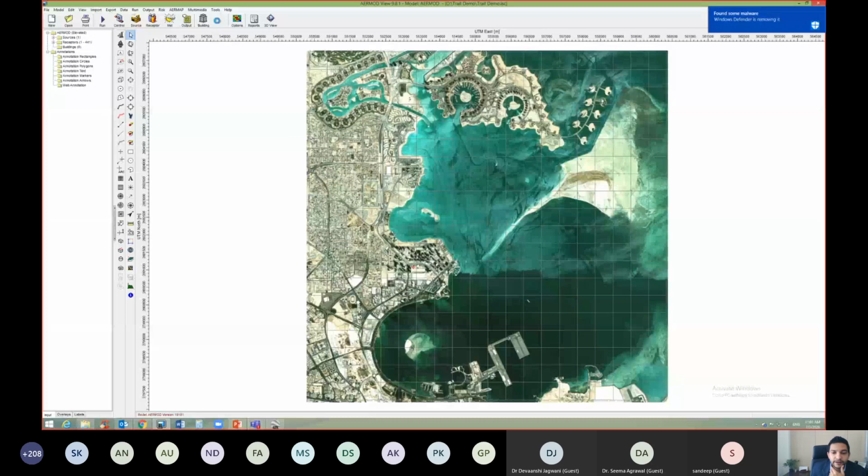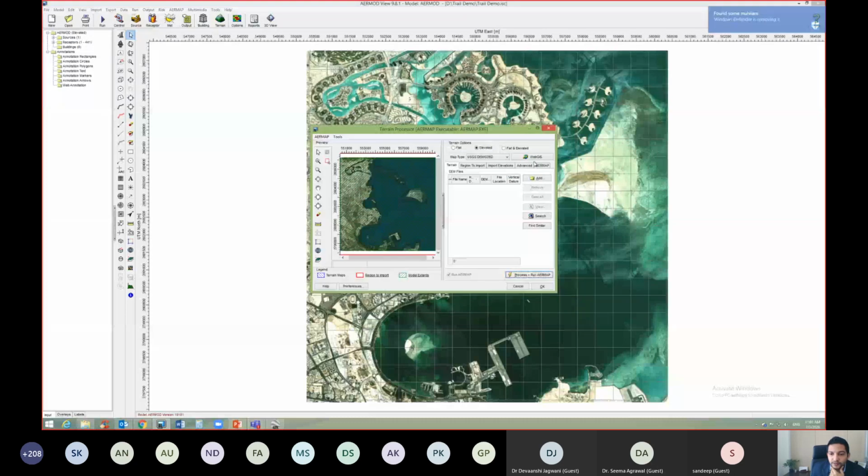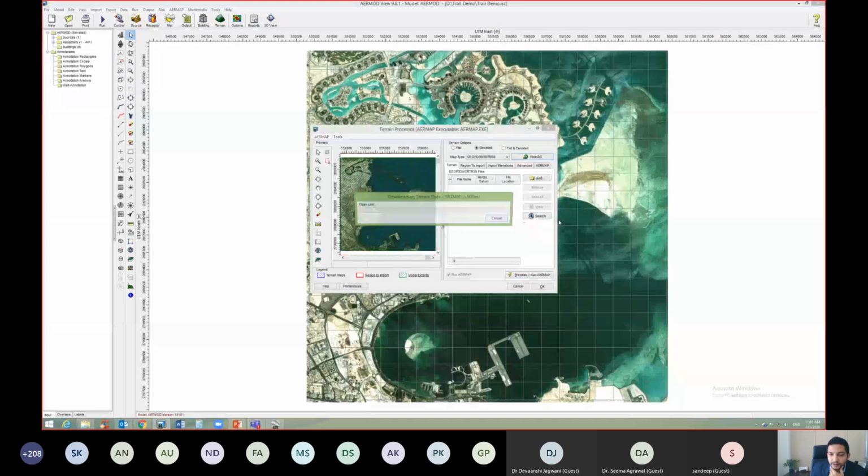And then we go to the terrain, and we process the terrain from the WebGIS website. The WebGIS website has data for all regions, detailed terrain data. This topographical data is directly downloaded from WebGIS with a resolution of 900 meters.